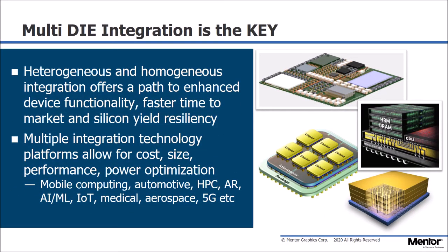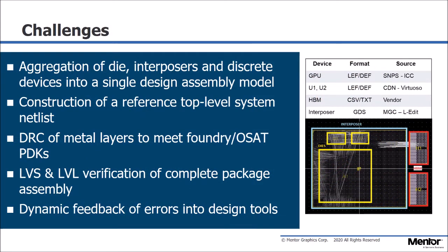The real strength of HDAP packaging is its heterogeneous integration capabilities, where devices of different technology nodes can be integrated together, providing the performance, size, and power consumption and cost requirements that multiple markets demand that in the past could only be achieved using a monolithic single device approach. But such advanced IC packages also come with a number of challenges, many of which are new to IC packaging.